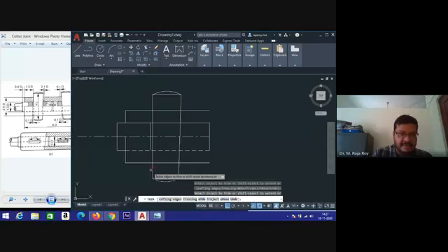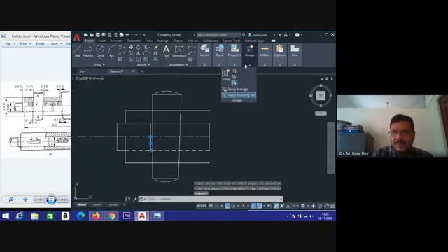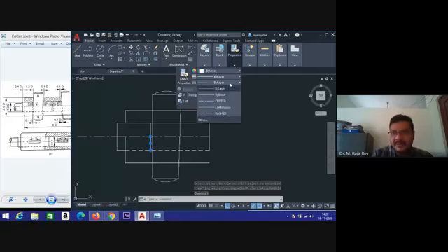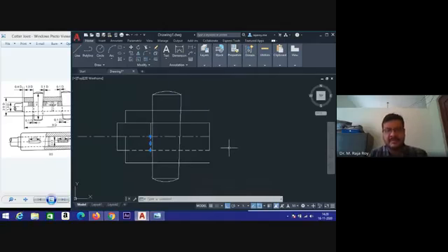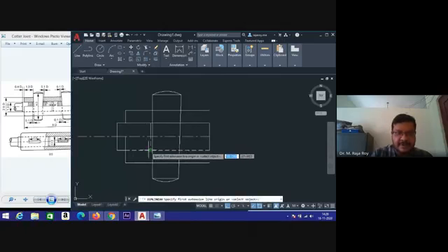Okay, you can delete that. Next, this particular line, we have to convert as dashed line. Then go to properties, select dashed. That will be the dashed line. Then here to here, this is the dimension line. Just go to dimensions, add the dimension line like this.